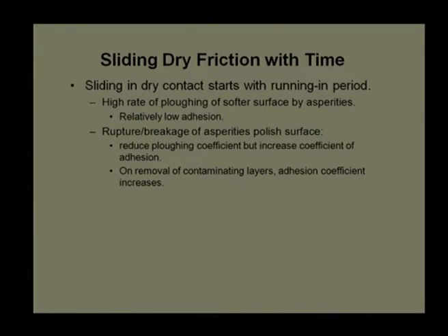Running-in time we are not counting, and for the remaining number of hours which that tribo pair can sustain, it will show a steady nature of coefficient of friction. We are talking about that. However, there is a possibility of change in coefficient of friction even under steady running condition. When we bring two new, fresh surfaces together, there will be a higher ploughing effect at the start and relatively low adhesion.